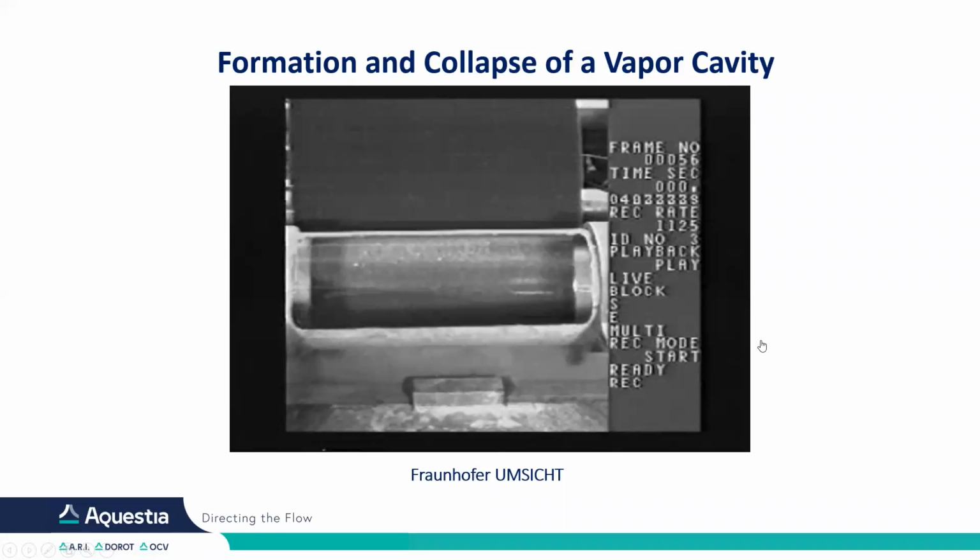Now, this happens very, very fast. This is why you have this slow motion video that shows you. You can see the time. And you see that it happens very fast, less than 1 second, everything happened, the formation of the vapor cavity. And that's why the protection that you need to give to the system needs to react very fast. When you have that formation of the vapor cavity, you need to very quickly admit air to avoid that vapor cavity.